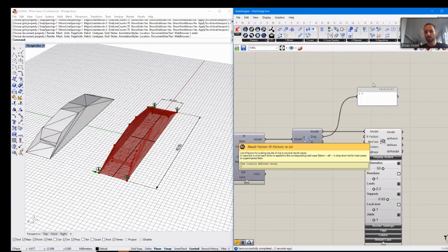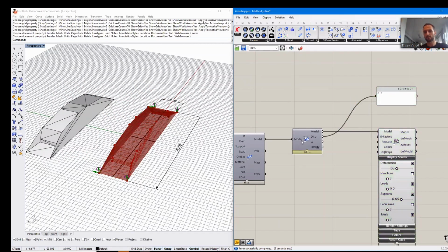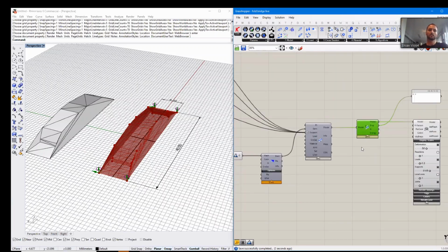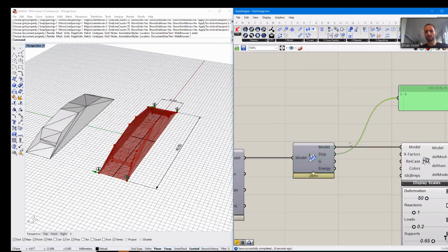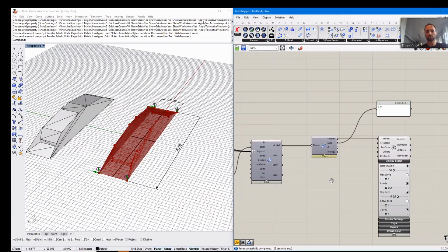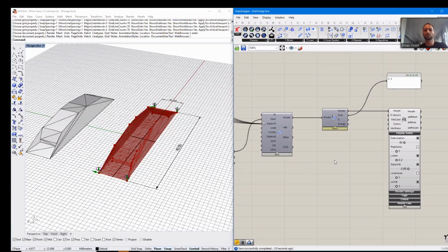And now, what I told you before about typical optimization goals: sometimes I could now apply a load and optimize the stiffness of the structure by minimizing this displacement value. But sometimes it's difficult to come up with a load scenario which is universal enough, because the application of loads and its effect on the structure and the bearing behavior to sustain those loads is kind of special in some situations.